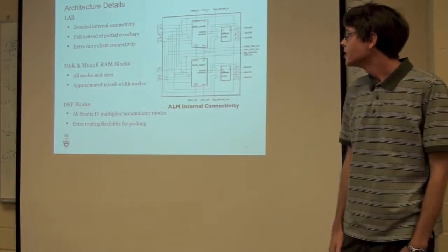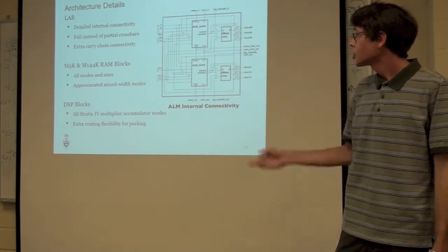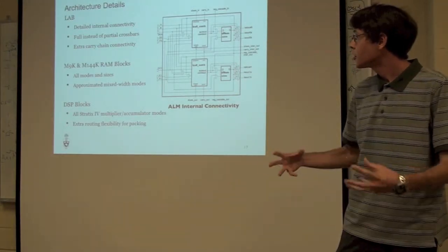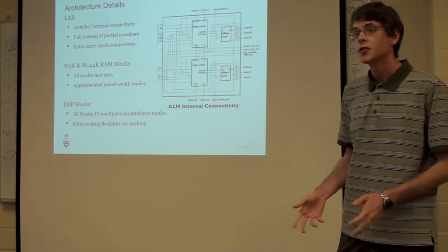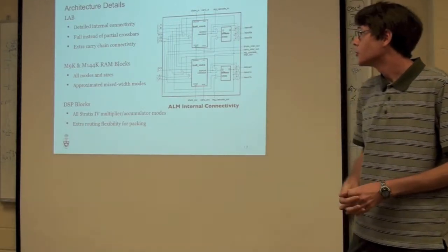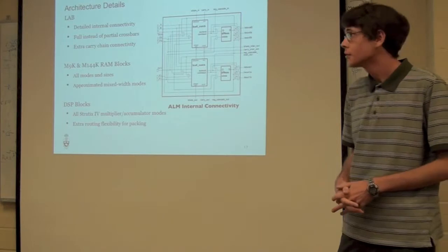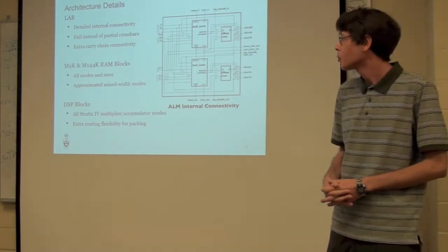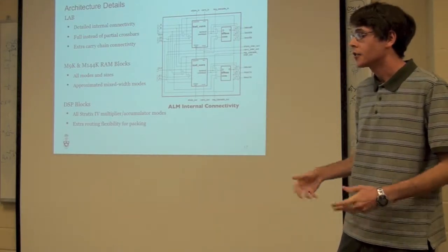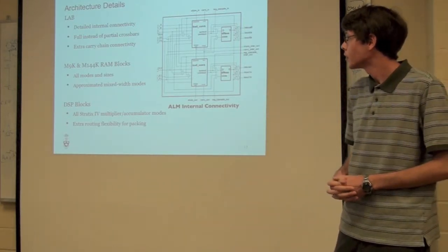Looking a little bit more at the details of the modeling, for the logic array block, we try and model as much of the internal connectivity as is practical. Although we did have to make some approximations, particularly using full instead of partial crossbars, and also had to, because VPR didn't support carry chains at this point, add some extra connectivity so carry chains would work properly.